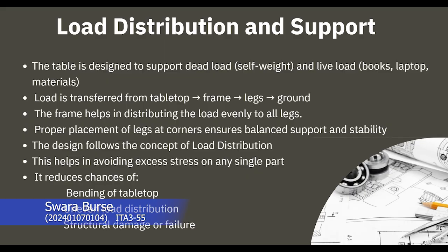The frame ensures even distribution of load across all four legs, and the corner placement of legs provides balance, support, and stability. This reduces stress concentration on any one part and helps prevent bending, uneven load distribution, and structural failure. So, the design ensures strength, stability, and durability. Thank you.